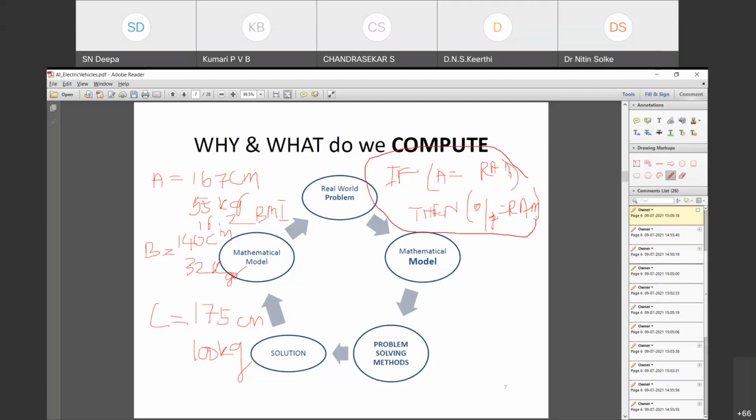So this is expert system modeling. Whenever they use sensors, if you see a person at this distance, 25 centimeters, these are all if-then statements. If your AI is going to be computing algorithms, it will be different, with procedures, and each time the learning factor might be updated. But when I'm designing an autonomous electric vehicle for a short distance, I can go for expert system rules, and these rules are primary for autonomous vehicles.